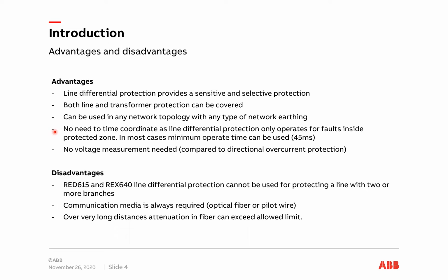That also means that when we are operating for faults only inside the protected zone, we can, in most cases, use an operate time which is at minimum 45 milliseconds for this protection. And only three-phase current is required. No need to use voltage measurement like you need for directional overcurrent protection.